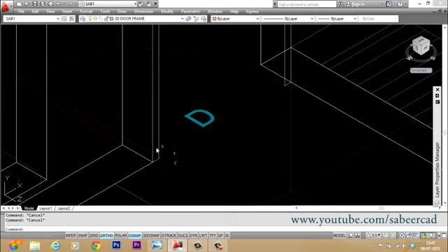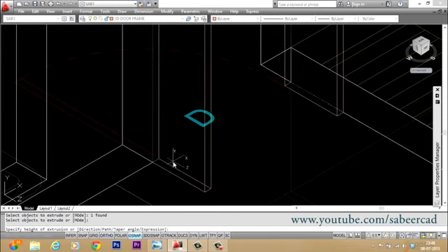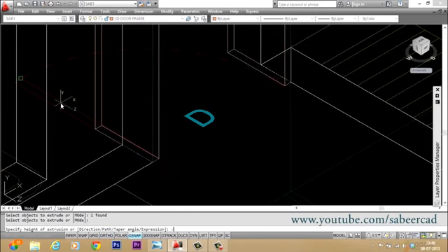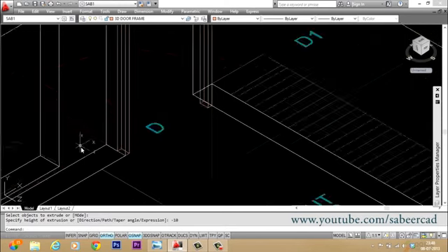Now you can extrude this profile in the negative Z axis direction through a distance equal to the thickness of the frame. And I gave the extrude command. Now when I'm asked to give the thickness, I'll give -10, because that is the thickness of the frame. So we have made the door frame.